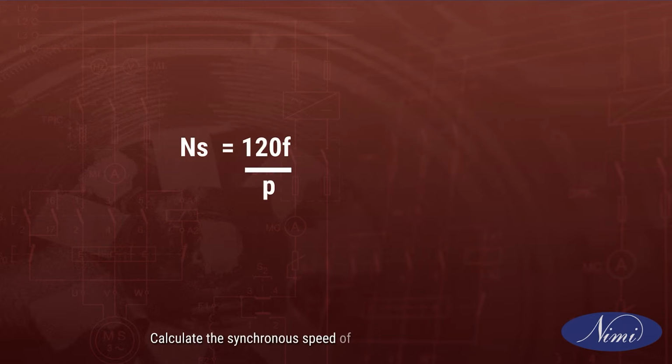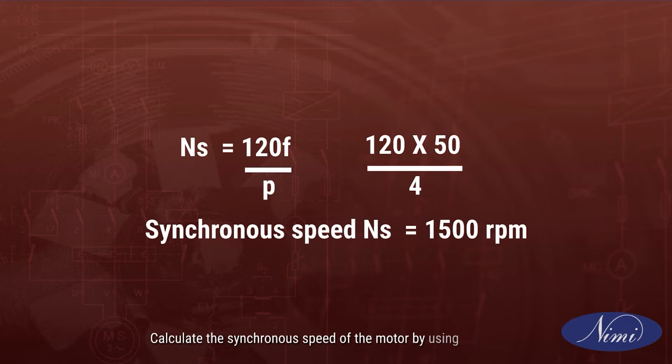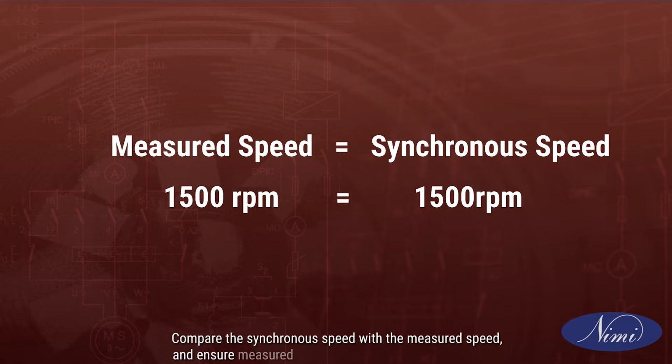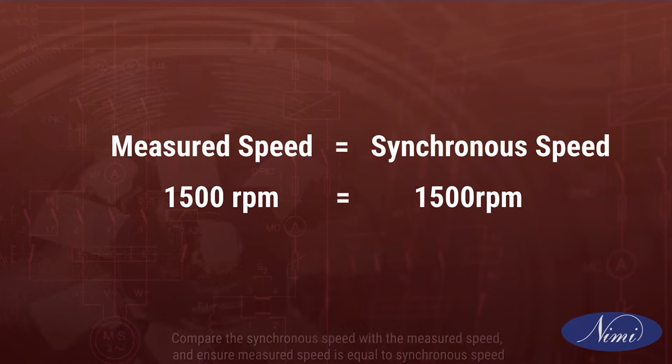Calculate the synchronous speed of the motor by using the formula. Compare the synchronous speed with the measured speed and ensure measured speed is equal to synchronous speed.